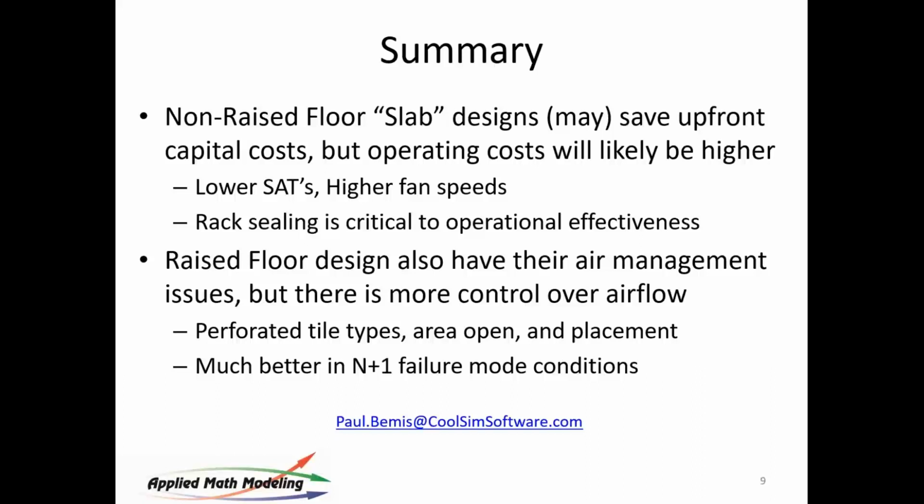Be sure to point out leakage. Be sure to model leakage and understand, particularly in the N+1 case when one of those air handlers is off, how the system's going to perform. Be careful of having rack rows too close to fan walls or other high-speed air devices that are moving in a horizontal direction or perpendicular to the server itself. And use CFD to try out different scenarios.